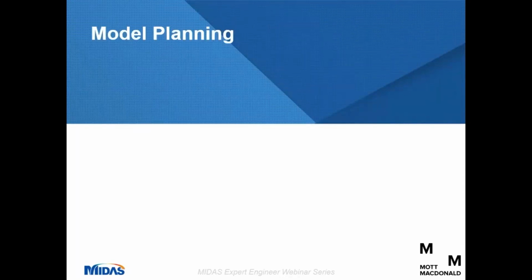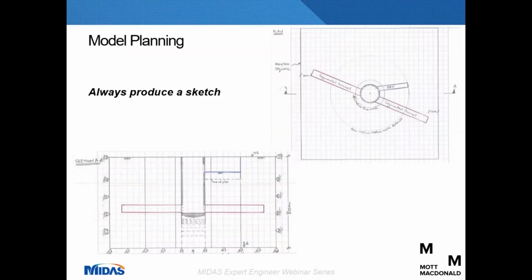So one of the key stages in the development of any numerical model is the planning. And this is particularly important for 3D modeling, where model runtimes can become quite large, so mistakes in the model can lead to a lot of abortive work. So making an extra big effort early on in the process to properly plan models is invariably time well spent. So part of this planning should include production of sketches that define the model geometry and boundary conditions adequately.